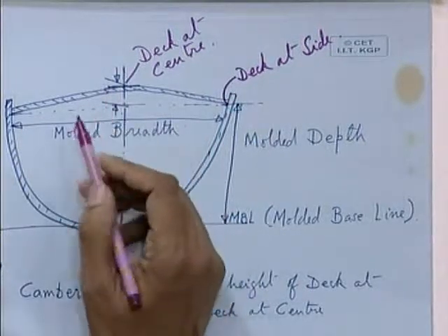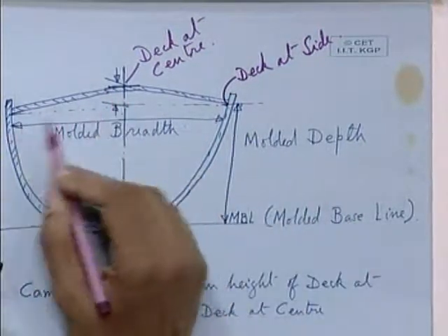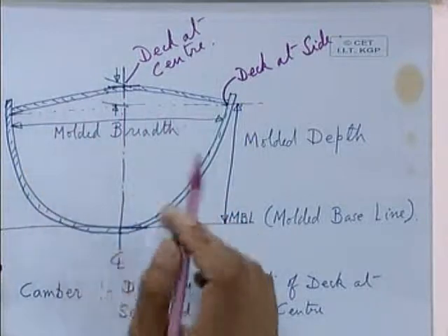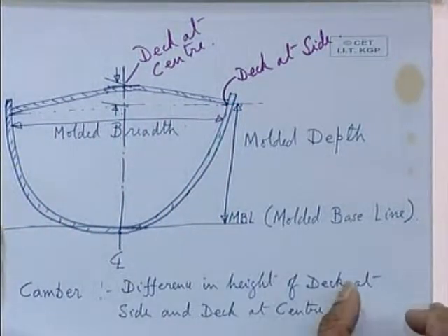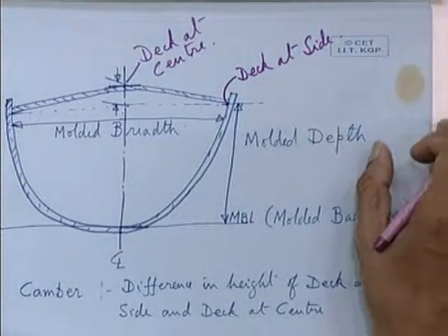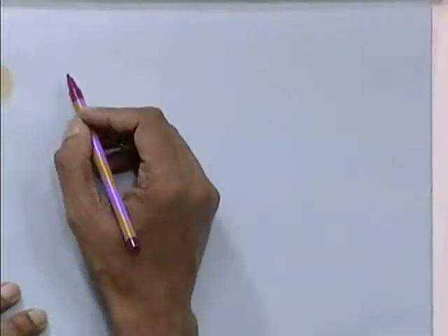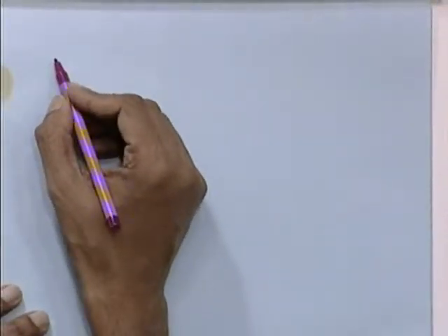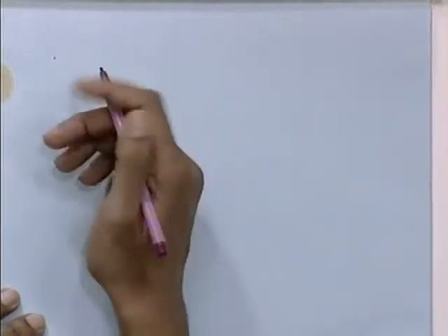Normally in roads also you will find camber, given especially for draining. Otherwise, the crew does not want to work on a wet deck. The ship's deck has to be maintained dry for the safety of the crew. He should not slip on the deck, and by slipping he should not fall overboard. So that is why the camber is given.